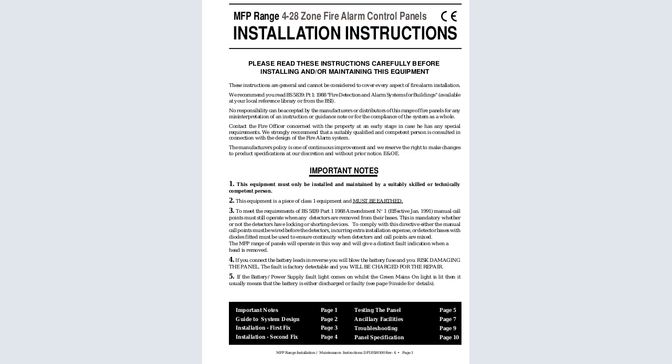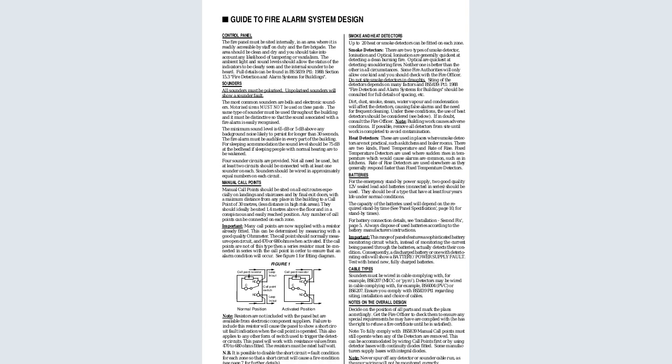If the battery or power supply fault light comes on whilst the mains are on, then it usually means that the battery is either discharged or faulty. Those are some of the basic instructions.